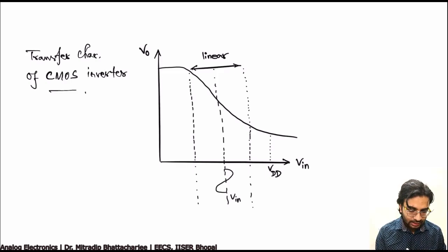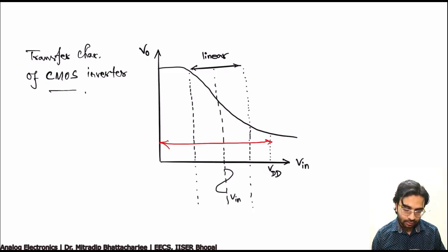So you will see digital can use the entire range. However, analog people will only look for this linear part. They will not go beyond the linear part. And why will they not go beyond? If they go beyond the linear part, other interference may come up, like A1x squared, A2x cubed, something like that. Once this interference becomes dominant, you are going to lose power for nothing. So we don't want that to come.